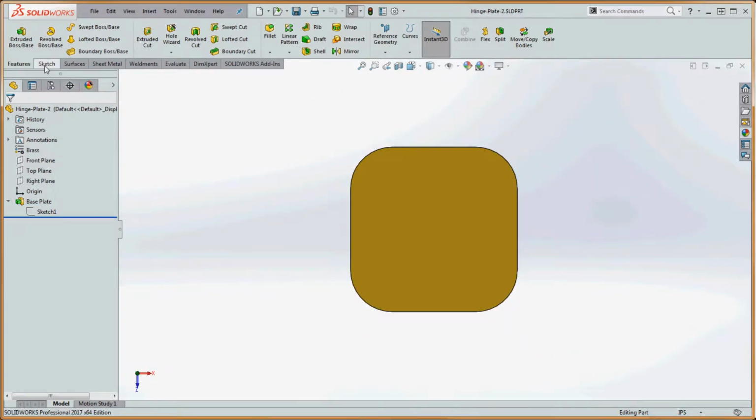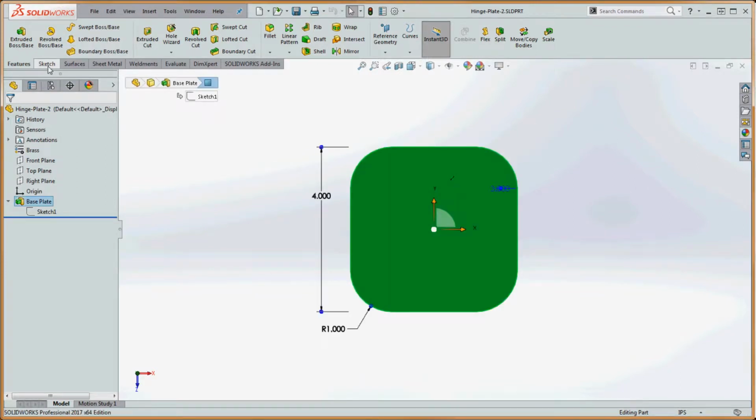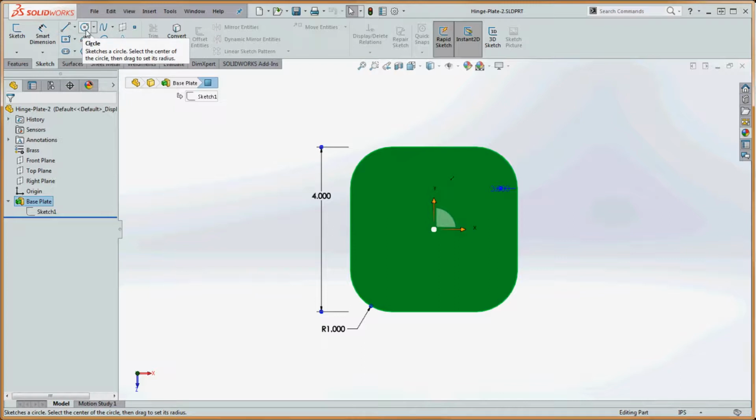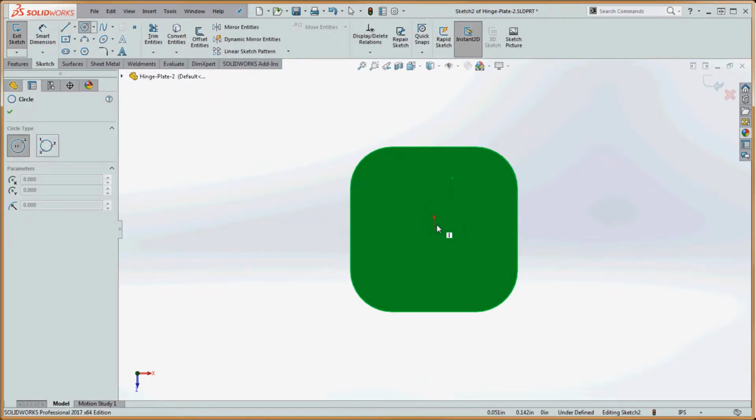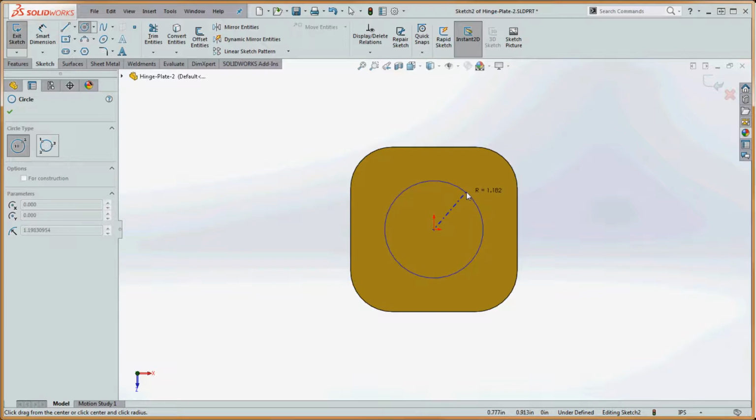Of course, the very easiest hole we can do, after choosing that surface, is to go to Sketch, go to the circle command, and what that does is sketch a circle out from a point that we select. In a very similar manner to the center rectangle, the circles do the same thing. We're going to drag our cursor in here, select the origin, and sketch that out. It's actually the projected origin onto that surface. And we're going to sketch a circle out.